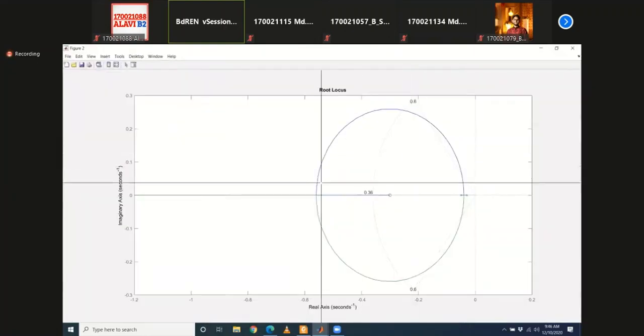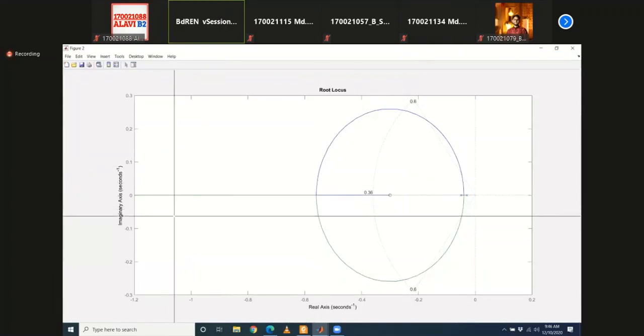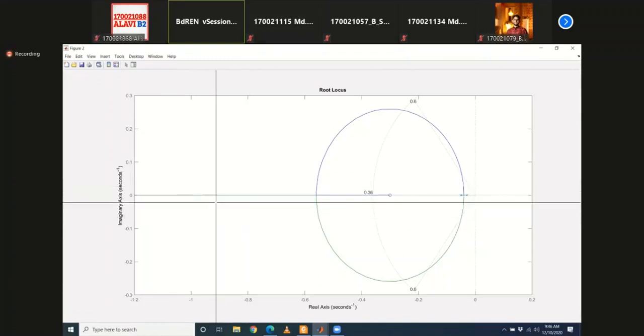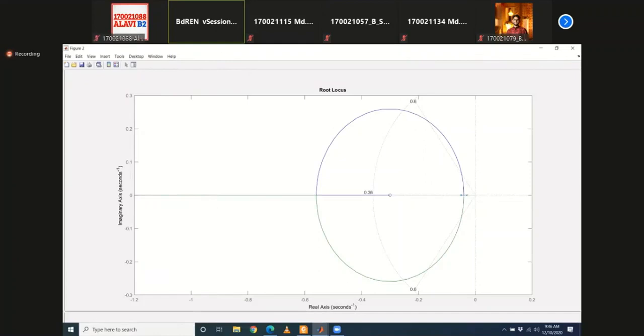So again, we have obtained the root locus diagram and also the zeta and omega n locations, basically. Just by looking at this root locus diagram, the colored portions are the root locus, right? Are they consistent with the rules that we learned? What were the rules? Poles will move to the zeros, and the root locus exists only to the left of an odd number of poles and zeros, right? So does this root locus diagram follow those two rules?